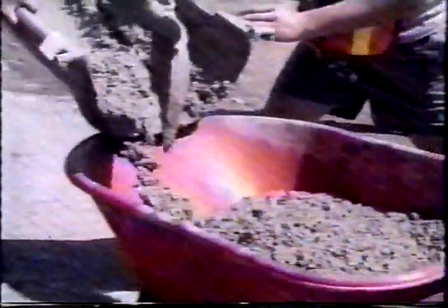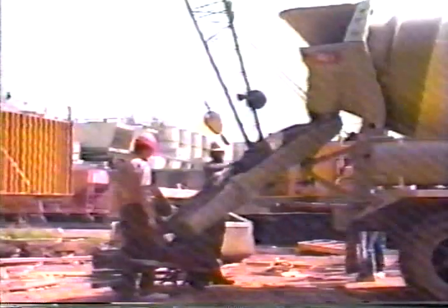Before any of the tests can be performed, a sample of the concrete is needed, a representative sample. The concrete to be tested has to be typical of the entire truckload. Sampling should be done according to AASHTO designation T141. The basic rule is this: don't take the sample from the beginning or end of the discharge. Take it from the first 1/3 of the discharge, but never from the first 2 cubic feet.